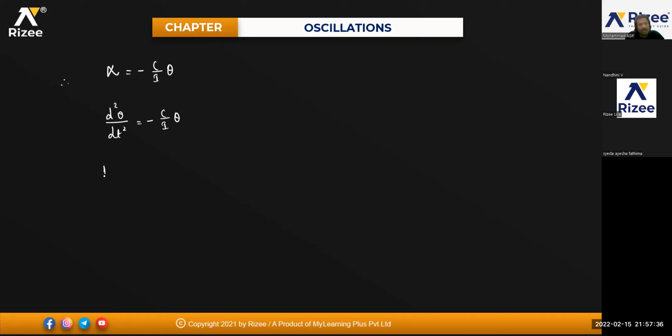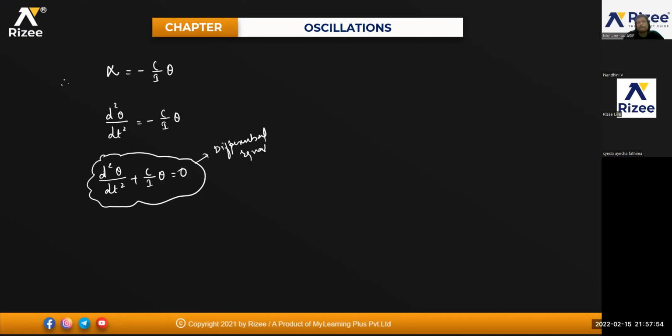If I take this term here right now, this is d square theta divided by dt square plus c by I into theta will be equal to 0. So this is your differential equation of angular SHM.